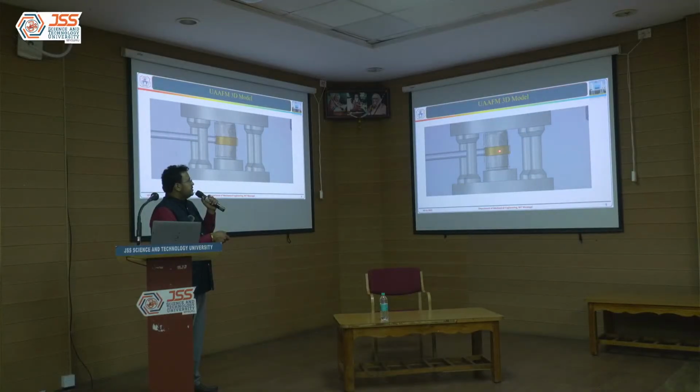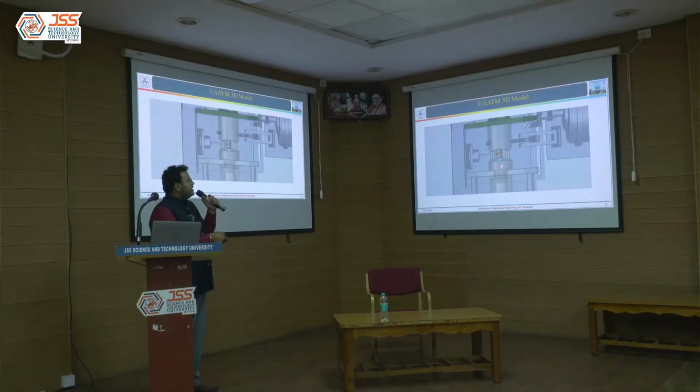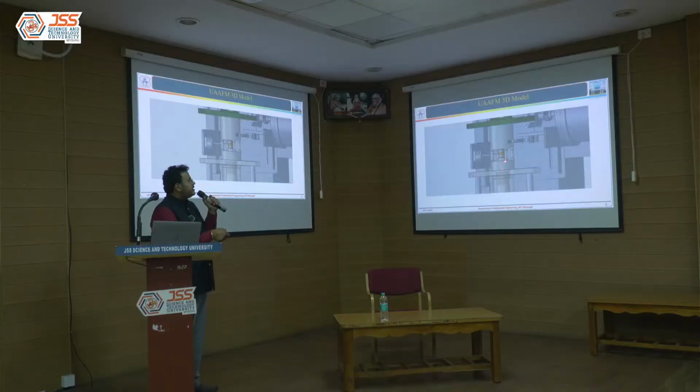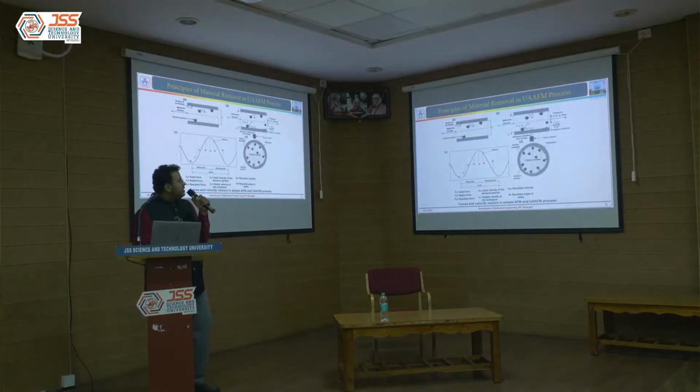Here we studied the simulation of the media behavior inside the workpiece when it is vibrating at high frequency. In a simple AFM, what is the media behavior inside, and when we vibrate at high frequency, what happens to the abrasive particles hitting the target surface, and what is the temperature distribution, velocity distribution, and wall shear distribution during the simulation?